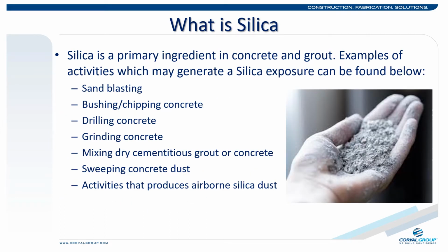Silica is a primary ingredient in concrete and grout. Examples of activities which may generate a silica exposure can be found below: sandblasting, bushing, chipping concrete, drilling concrete, grinding concrete, mixing dry cementitious grout or concrete, sweeping concrete dust, and activities that produce airborne silica dust.